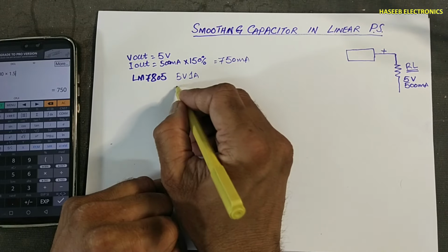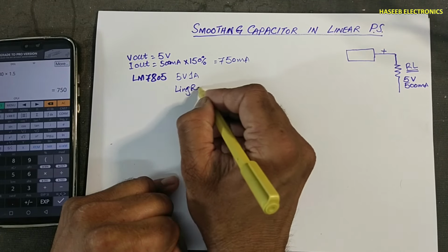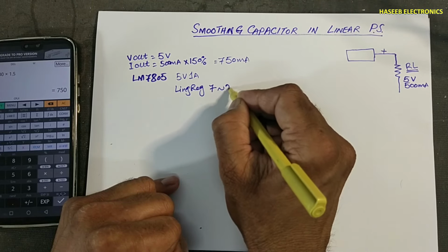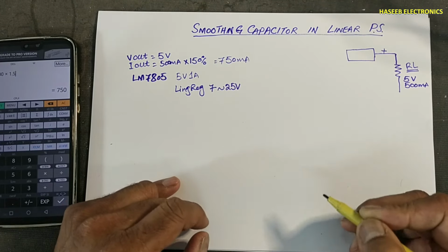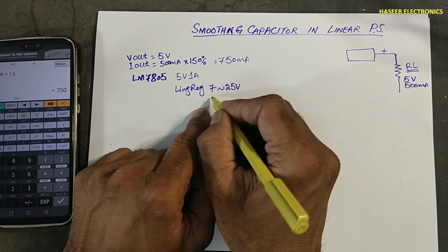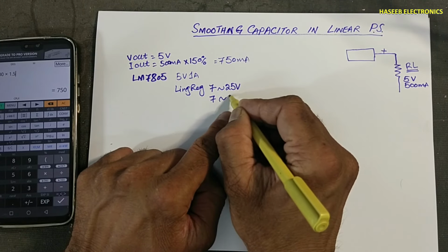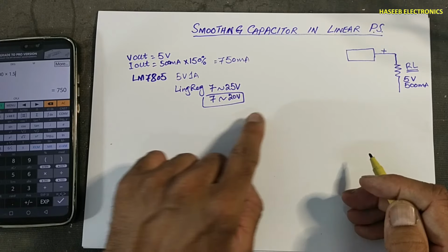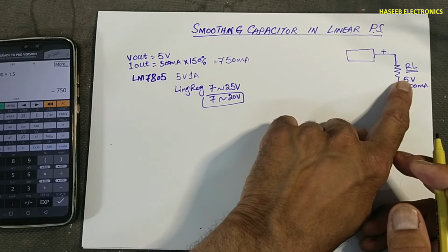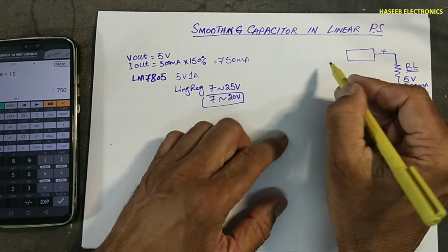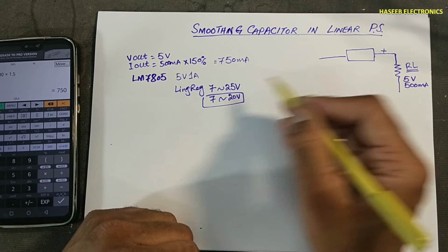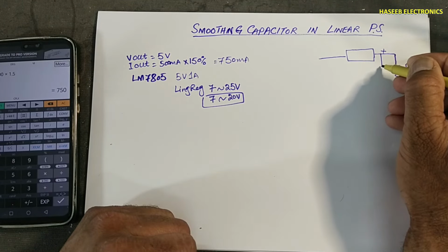when the line regulation is 7 volt minimum up to 25 volt. The normal range is considered 7 volt to 20 volt. So this is a good line. So it will provide regulated voltage, and when the voltage drops at this point until 7, it will still provide 5 volt.